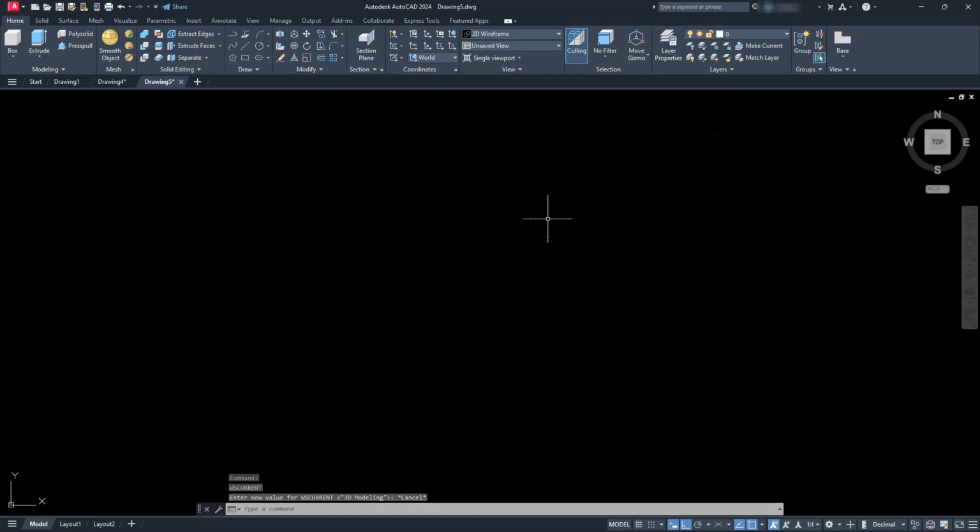Alright, so like I say, the modeling on this is going to go super fast, right? And it's going to work almost the same as what you saw me create when I did the 2D drafting of this. Alright, so we're going to start off with a circle, and I will be using the shortcut commands for this, so I'll try to explain to you. This is going to be a lot quicker than going up here and picking the icons. So I'll start off with C, enter.